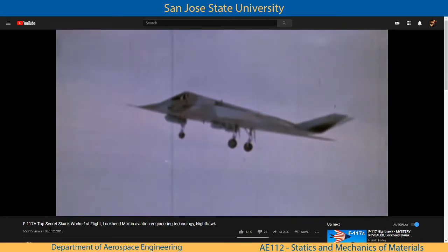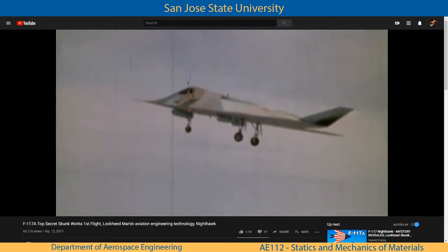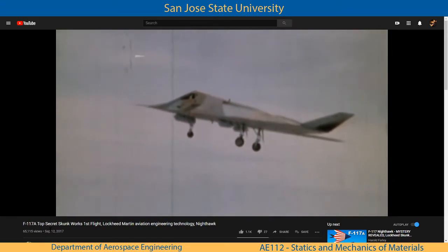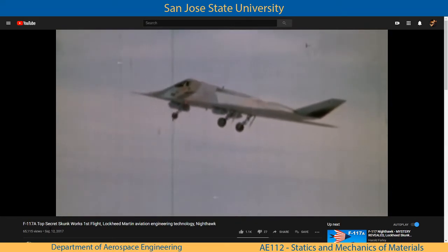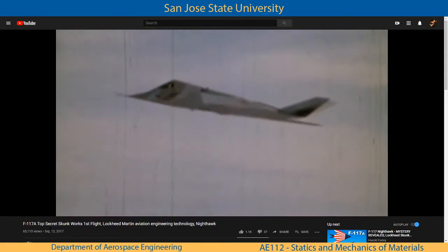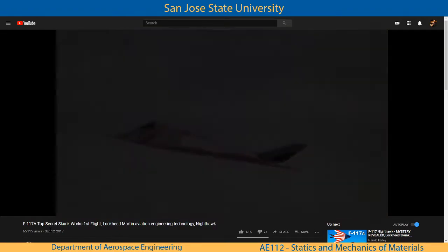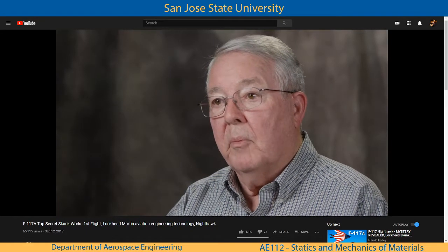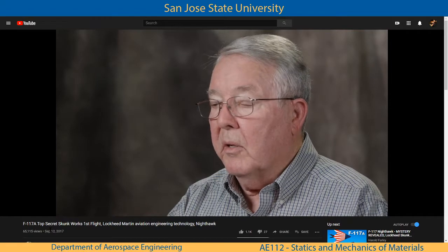And we flew the airplane 6 more times in a very limited flight envelope while they were building a new set of fins 50% bigger that were put on the airplane. And from that point on, we had the proper amount of stability. That was the big thing learned on the airplane. The minor problems that we encountered are not minor, really.